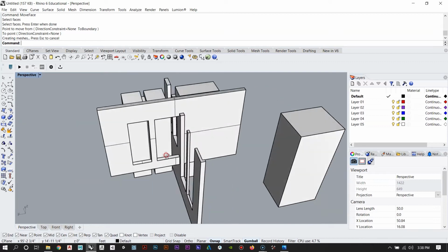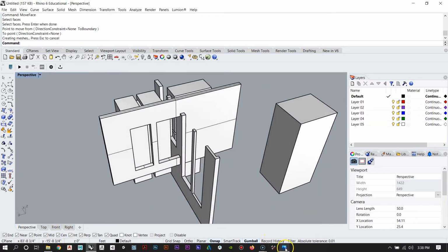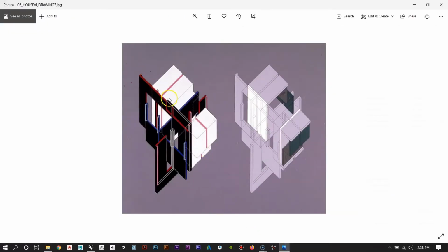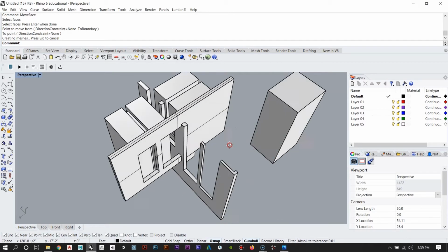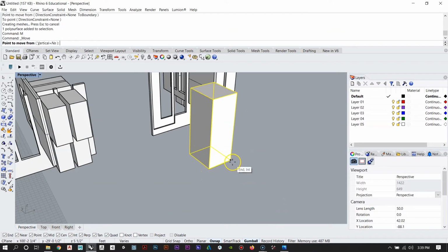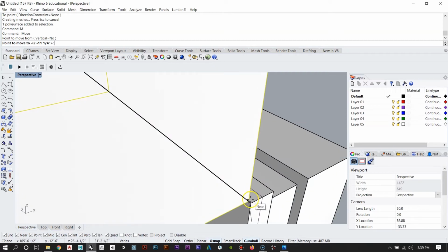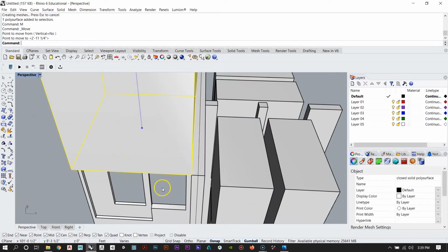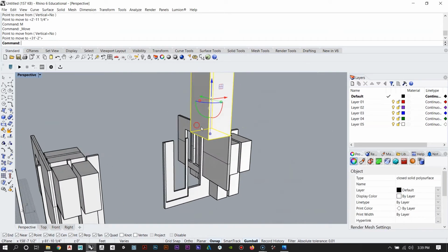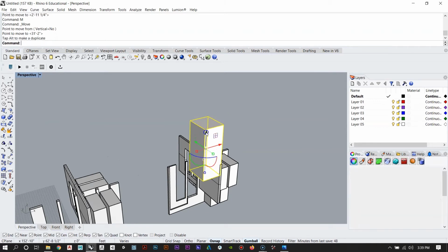And then the next thing we can do is come over to the other plane. And it looks like these were done from the back side on these two, and then from the other side on these two. So let's create these two notches first. Again, I'm just going to stick with this piece of geometry. First, I'm going to snap it so I know it aligns. And then I'm going to push it in halfway, so I'll align it to the midpoint. And then pull this down.